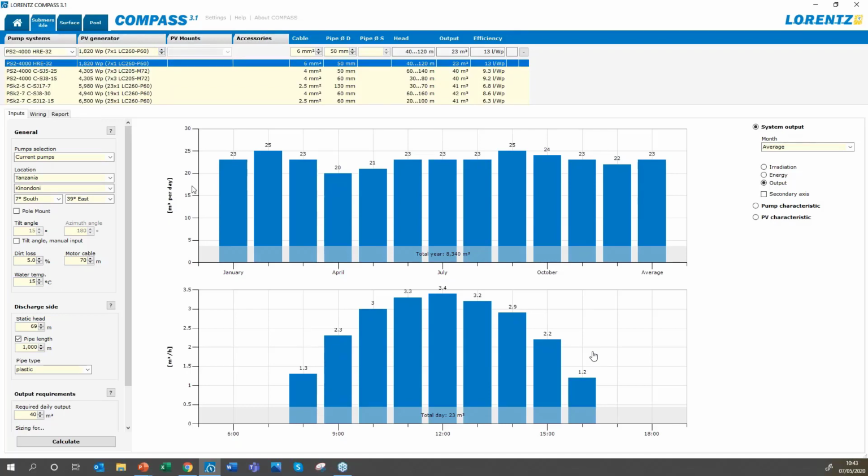So we could give the customer a couple of options here. We could give him the first sizing that we did, which was the PS 1800 with 1.8 kilowatts, something like that, giving him 20 cubic meters. Or a second alternative would be, actually, if you really want to add the next village on, you think in 18 months, why not buy this slightly bigger pump, the PS2 4000? Again, it's the same physical size, fits in the same borehole, but it's capable of more flow later.